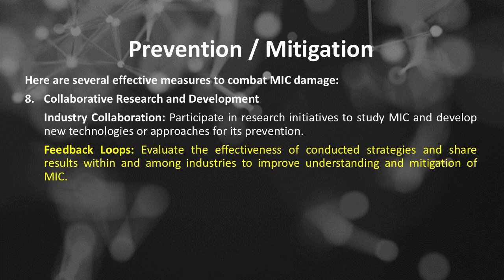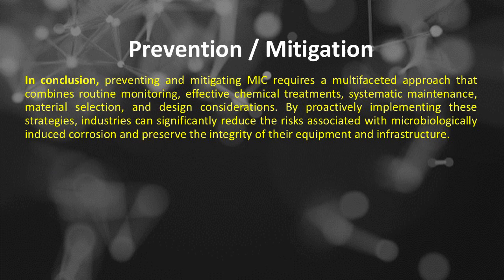of MIC. In conclusion, preventing and mitigating MIC requires a multifaceted approach that combines routine monitoring, effective chemical treatments, systematic maintenance, material selection, and design considerations. By proactively implementing these strategies, industries can significantly reduce the risks associated with microbiologically induced corrosion and preserve the integrity of their equipment and infrastructure.